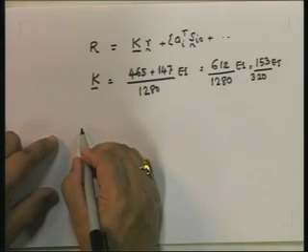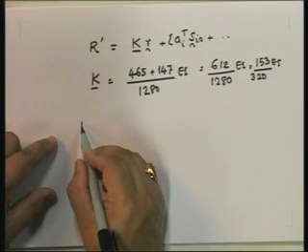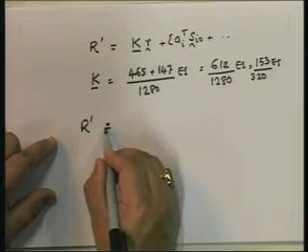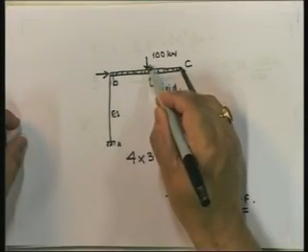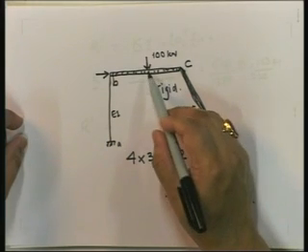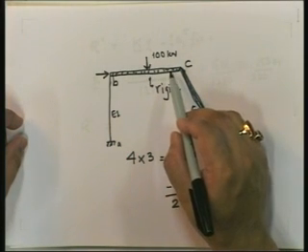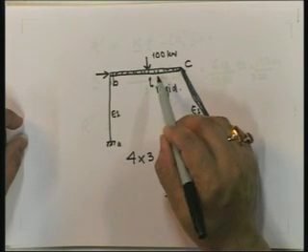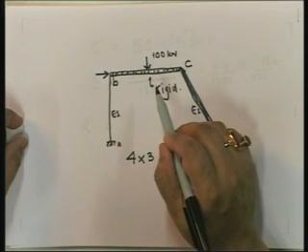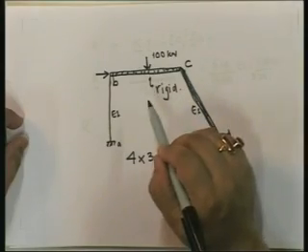Okay. And what is R? How do I get R prime? For R prime, note that even though in this particular case I have a load over here which looks like a load on a member, BC is not a flexible member, and since BC is not a flexible member, any load on a rigid member is considered equivalent to a nodal load.